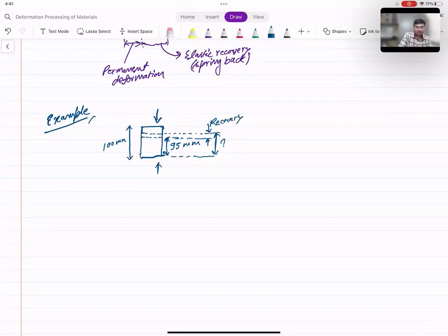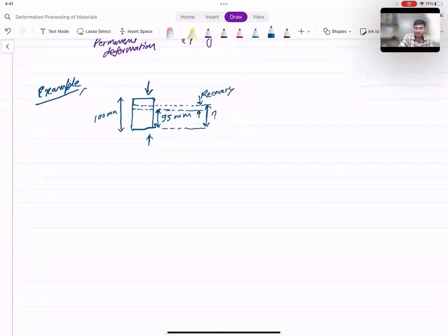I'm given some properties or fundamental characteristics of the material and loading conditions. So the applied stress here was 500 into epsilon to the power 0.10. Since this is a plastic deformation, this will be a type of flow curve relation. This will be a power law relation here. Okay, and the strain value epsilon here is true strain.